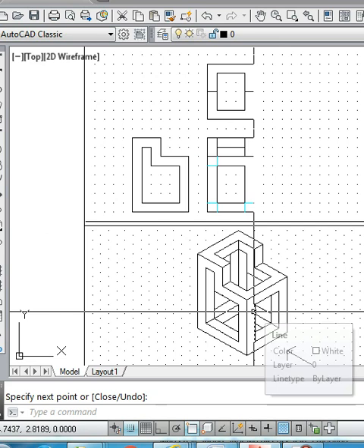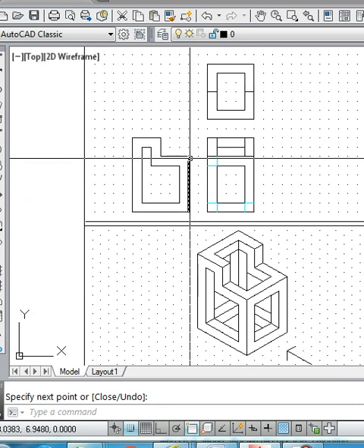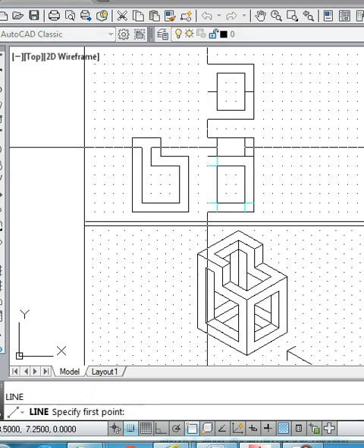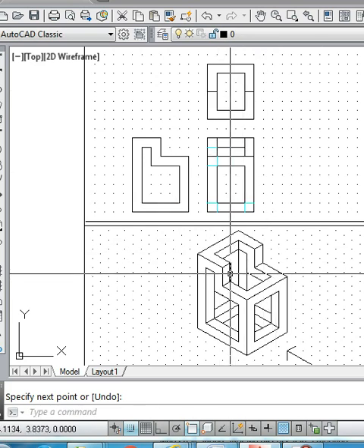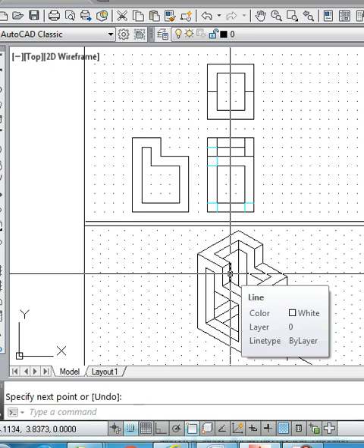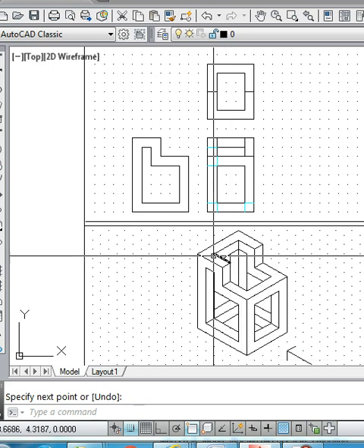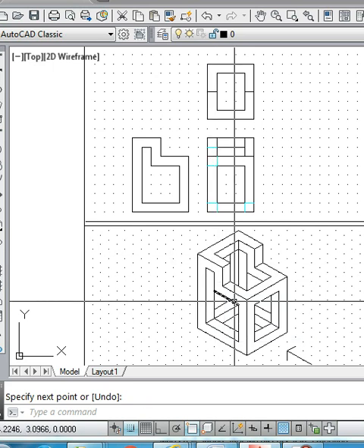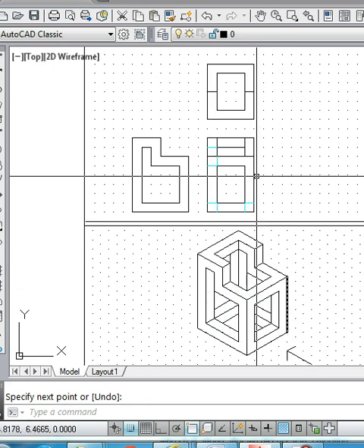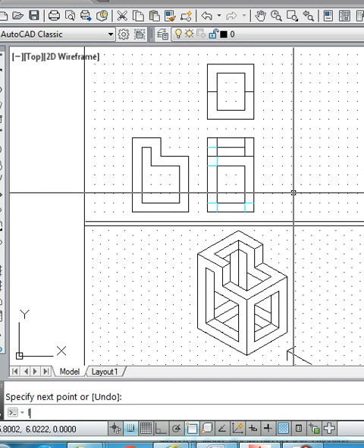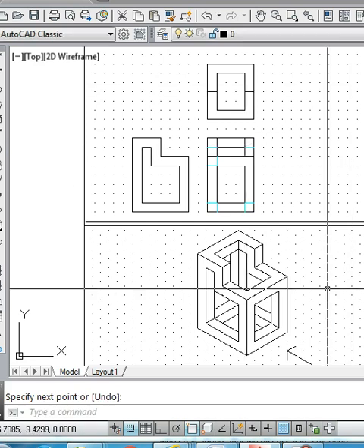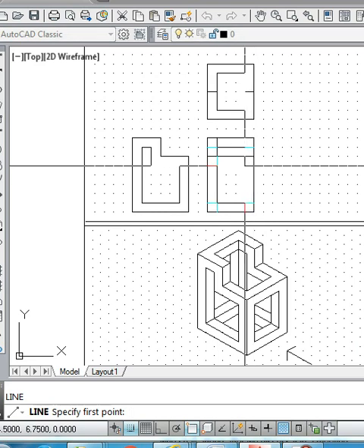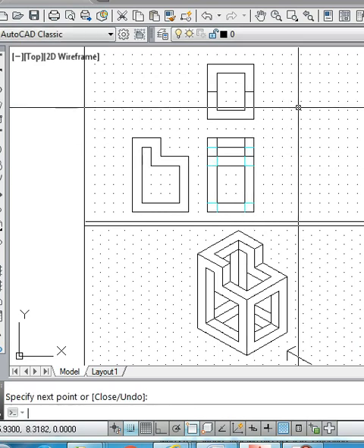Similar way, the edges are there at this location even, so from here to here. Even there is a vertical edge, but overlapping that there is a visible edge also. So the visible vertical edge is coinciding with the other edge which is behind. So that itself is also visible, so for that a solid edge is there. But on this side we have the hidden edge. So this way we shall see the hidden edges at these different corners.